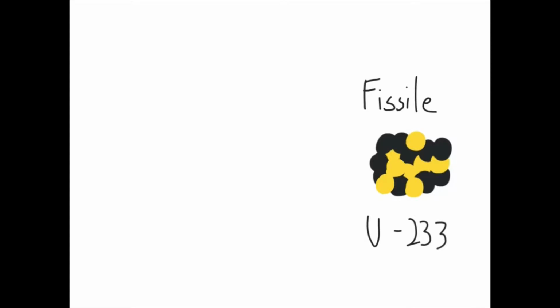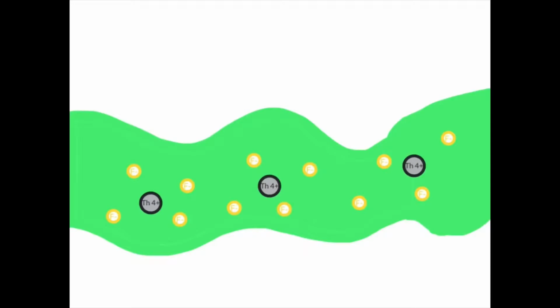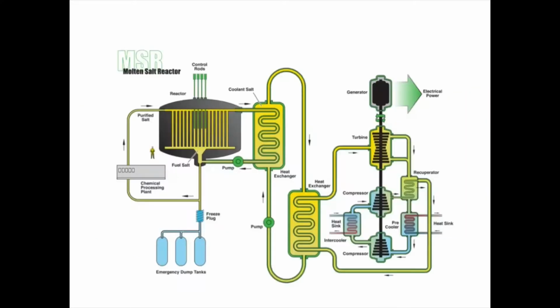This reactor is also unique in that its fuel is a molten thorium fluoride salt that doubles as the coolant and the fuel source, and it offers some unique advantages I'll discuss later. Liquid thorium fluoride reactors are different from fast neutron reactors in that they can be thermal reactors with moderators. Even though the fuel circulates through the entire reactor, not just the core, the moderator is only in the core, so it is much less likely for fission to occur outside the core where there is no moderator.